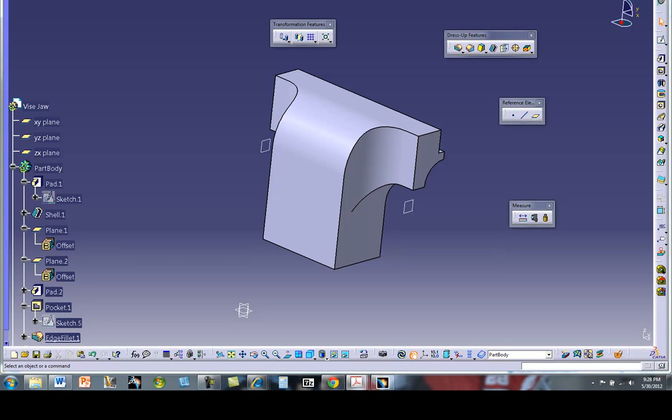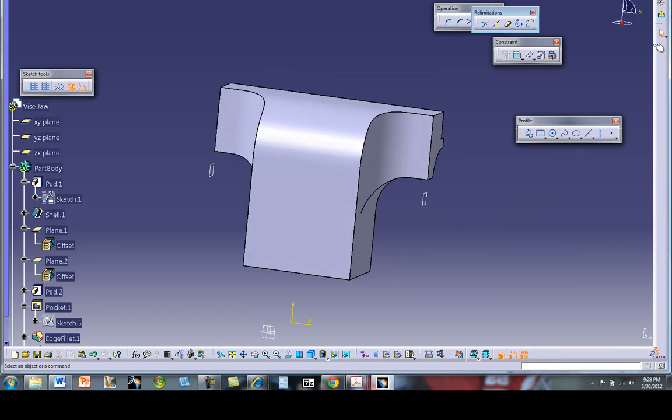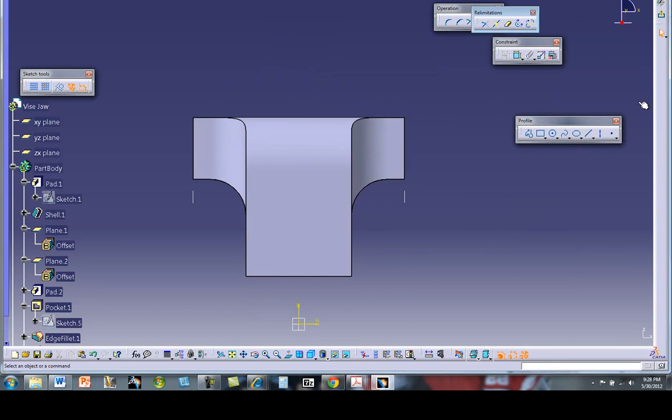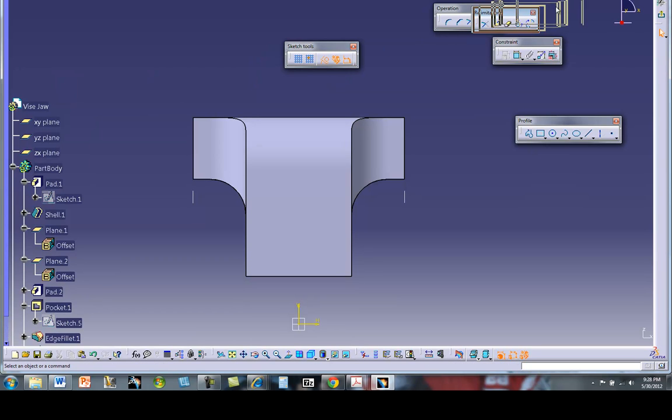So let's go over here, and I want to grab this plane as my sketch. And again, I'm going to use some project geometry methods here. So I know that if I look at my dimension here, I need to project off this bottom plane. Well, let's change that to a construction line for my projection. So over here, I'm going to grab the project 3D, and I want to grab this line right in here. Notice it makes that a construction line.